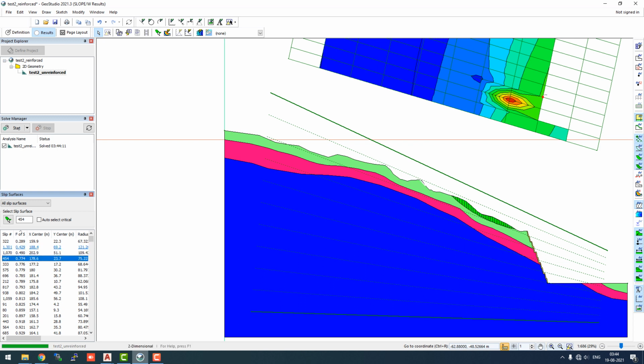But as soon as we move to the bottom, the various smaller failures which we have seen in the previous part are already gone, because the factor of safety jumped from 0.2 to 0.7 with only 2 variations. You can fine tune this analysis to see if there are any smaller critical surfaces available or not.